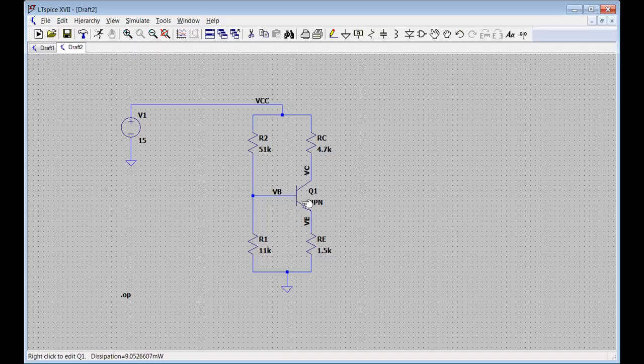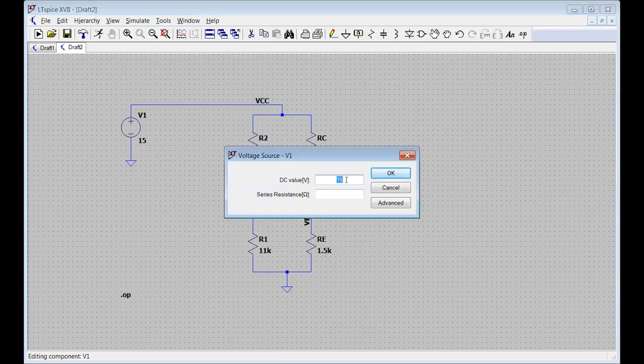Is the arrow here connected to your emitter? I believe so, but I can check. Well, you just have to look at it to tell. Yeah, it is. Okay. I'm not sure what you're missing then. Do you have your supply voltage here set to 15 volts? But I have 15V right there. Does the V matter? Get rid of the V. It thinks the V is actually a prefix, like K, meg, micro. You don't have to put the units here because the units are over here. I bet if you get rid of the V, that will probably take care of your problem.